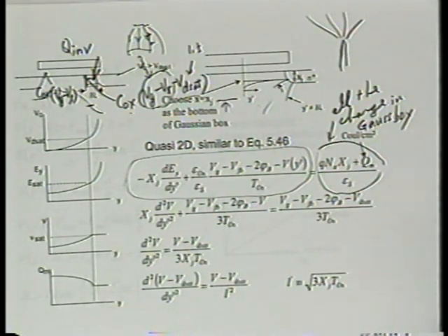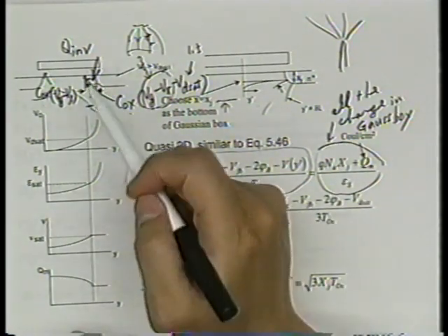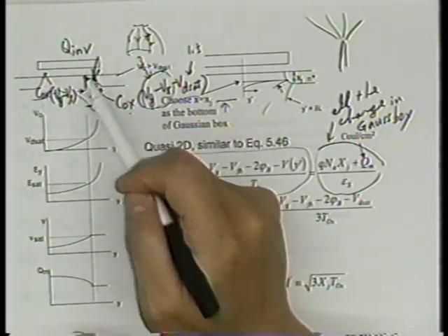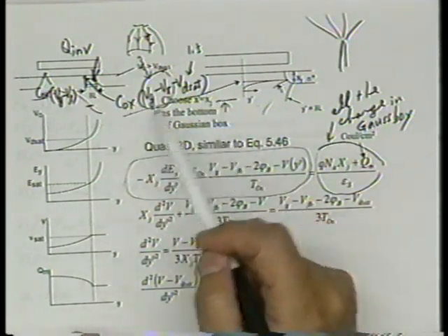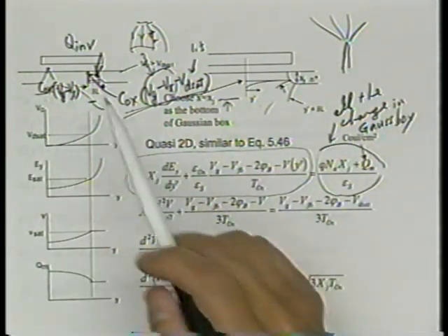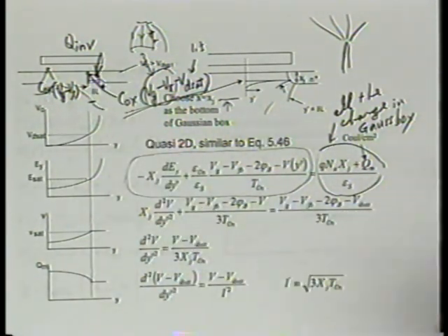I'll give you the answer, and I'm going to ask you for a justification. The answer is the charge density here is exactly the same as the charge density at the beginning of the pinch-off region, namely exactly the same number we wrote down before, which is only half of the charge density at the source. And that charge density remains constant throughout the velocity saturation region. Now give me an argument for that, a justification for it. Patrick, is that right?